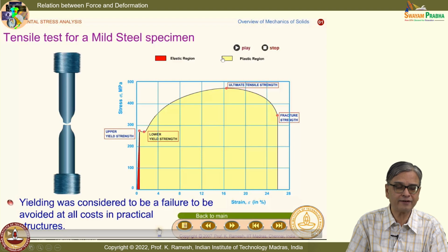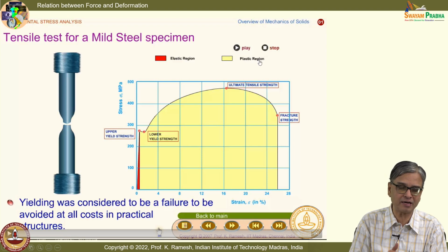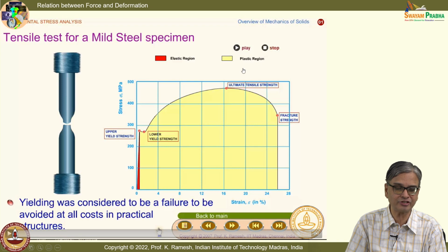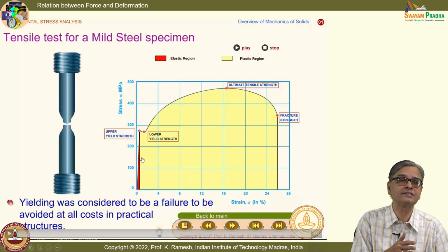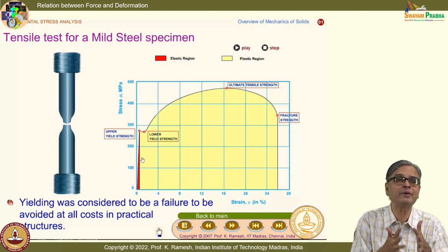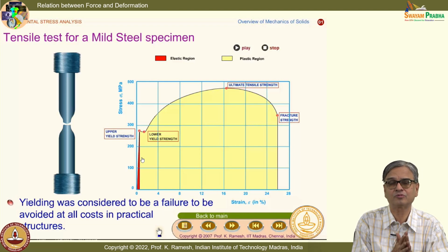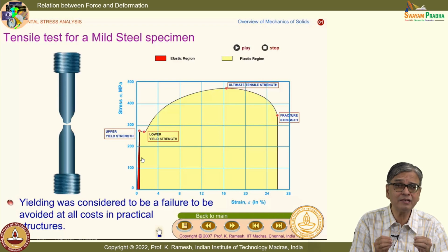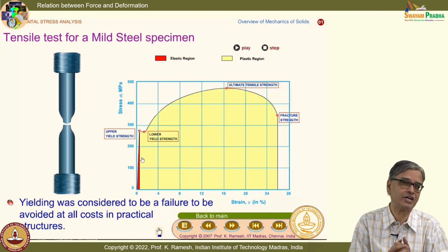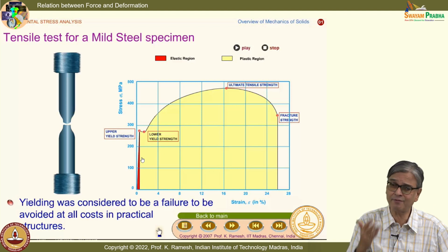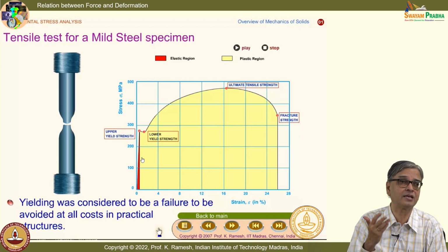This would be required if I have to design a crash bar. I would like to have a good plastic region, and many of the engineering components work together, so they have to remain in an elastic region. So from a practical perspective also, we will live in very small deformation in many of the applications. In some applications, we will have to go to large deformation, large plasticity and so on, but those instances can be handled as special cases.